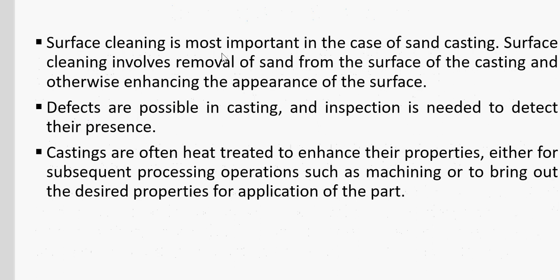And then surface cleaning is important in the case of sand casting. Sand casting may leave rough surfaces, so surface smoothness may not be good enough, so you have to clean the surface, right? Defects are possible in casting, and inspection is needed to detect their presence. So you have to inspect also if there are defects.